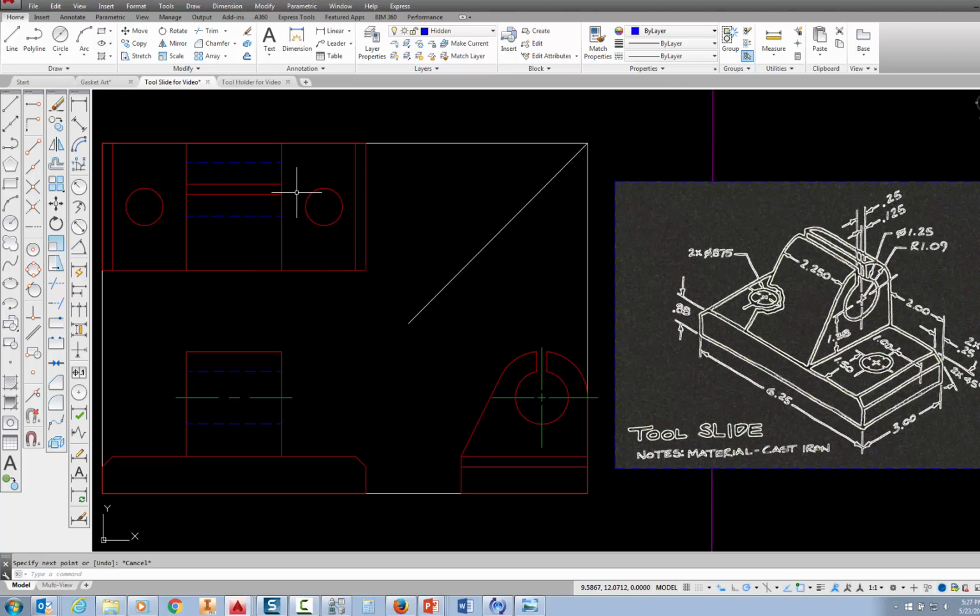Now the last thing I need to put in here is a center line that would be halfway between these two red lines here. So I'm going to change to my center layer, pick on that, pick on my line command, choose TT again, or temporary track point, go to the end point of that center line, follow it straight up, pick at the intersection, follow that across, pick at the visible line, come across, pick at the perpendicular on the opposite side, and press escape.